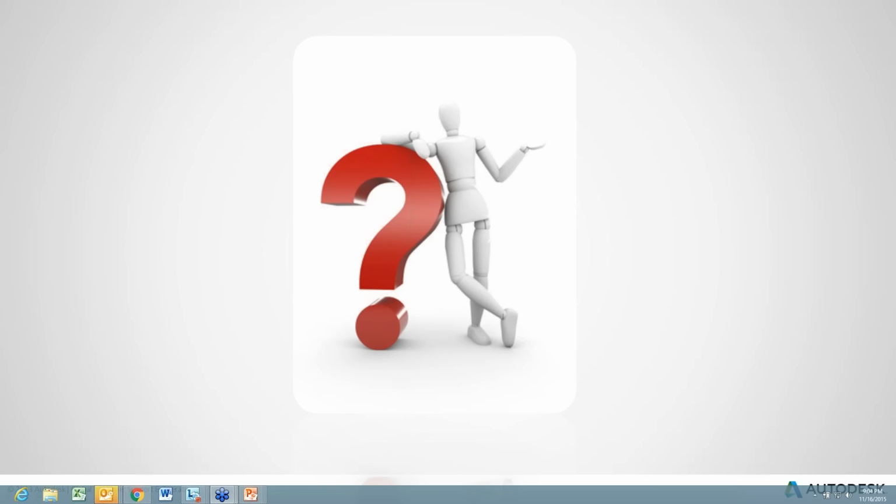All right, here's another question. Can we change the standalone installation to a network installation? Usually the answer is no, unless you do an uninstall and reinstall. If it's an AutoCAD-based product, there's actually a registry entry that normally you can go in and change. It's just either 1, 2, or 3 that will tell it whether it's a standalone, network, or multi-seat standalone. And so you can go in there and do that.